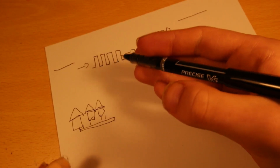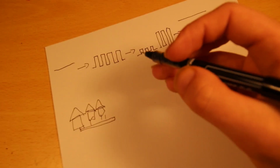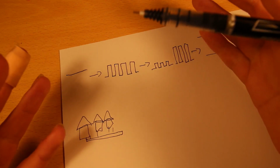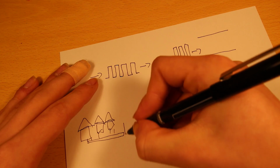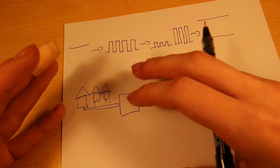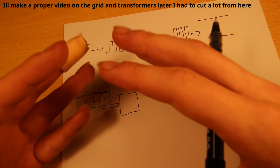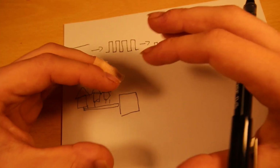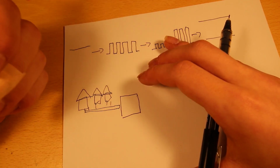At the end of your street, or depending where you live, there'll be somewhere fairly close by to you. My one is literally just across the street out my window. There will be somewhere a thing known as a substation, which is basically a place where they change the voltage. So there's a thing called a substation, which is basically a big box like this. I'll explain in more detail again how these work, but it has a component in it known as a transformer, because it transforms voltages. And the way the transformer works, it will have two or more windings depending on how it's set up. One of them is called the primary, and you apply power to the primary winding, and the secondary winding will then output a different voltage.